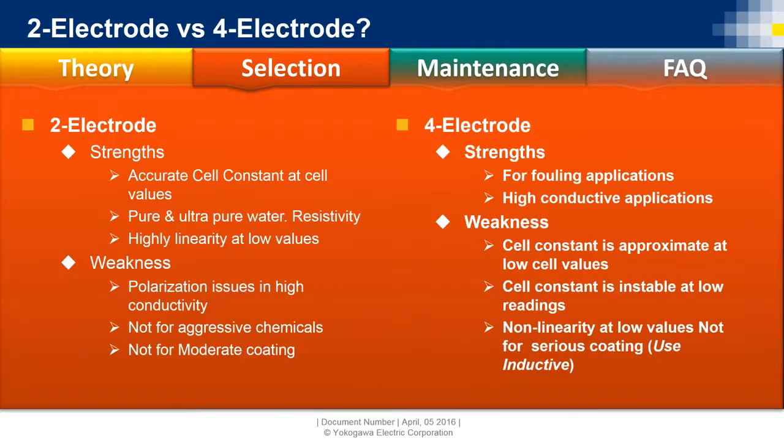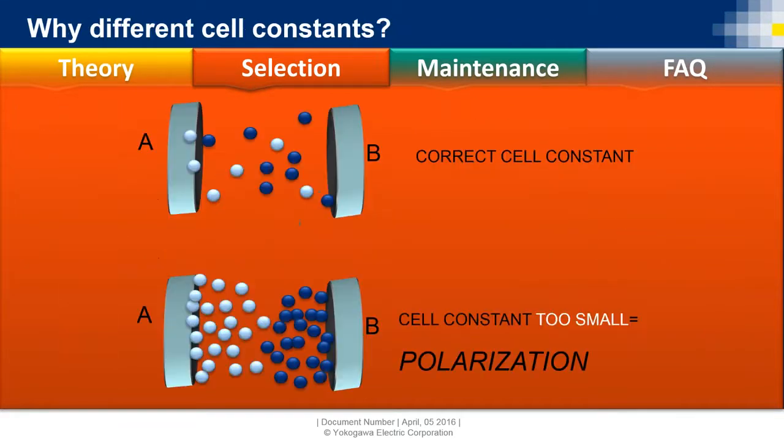Because when you go to extend the ranges of your sensor, you either have to A, change this multiplication factor, or you have to change the frequency output that the current alternates back and forth. And some vendors, Yokogawa is one of them, change the frequency. So automatically on its own, the analyzer knows, okay, I get to this point and I have to change my frequency, so it increases how quickly it alternates that current to extend the range.